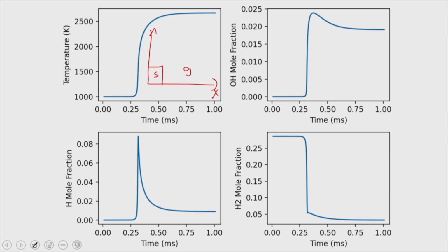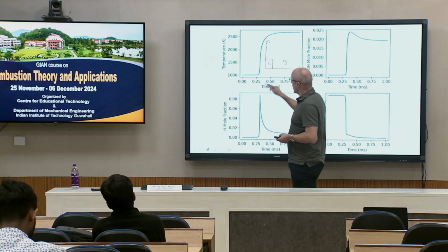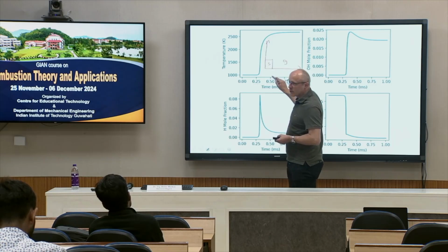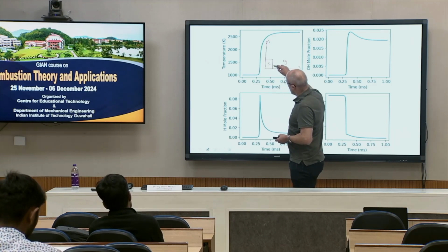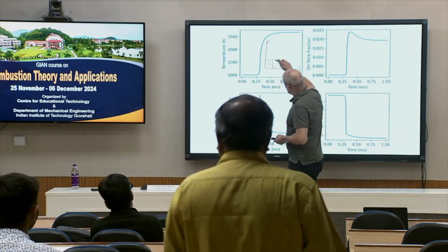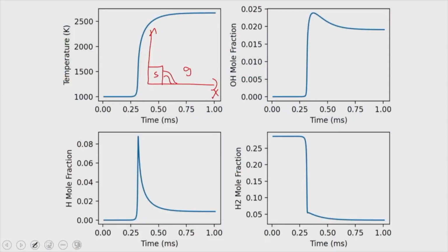And then the easiest solution is just to simulate the gas phase. So you can, for example, say here you have high temperature in the solid phase, and at the beginning the gas phase is quiescent and cool. So 2000 Kelvin, 300 Kelvin, for example. And then, of course, as a function of time, you see development of the temperature profile here, and after some specific time you see the ignition.